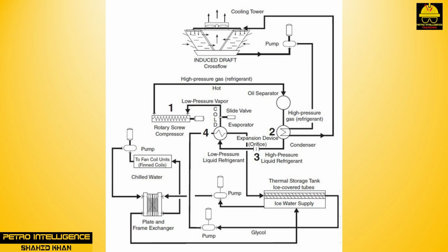If we pour a pound of propylene into an open container and watch it boil away, a thermometer inserted into the liquid will read -54 degrees Fahrenheit or -47.77 degrees Celsius. The heat for boiling comes from the container and anything touching the container, including the surrounding air. Moisture in the air will condense and freeze on the container and appear as frost. This is the sequence of events in a simple refrigeration cycle.